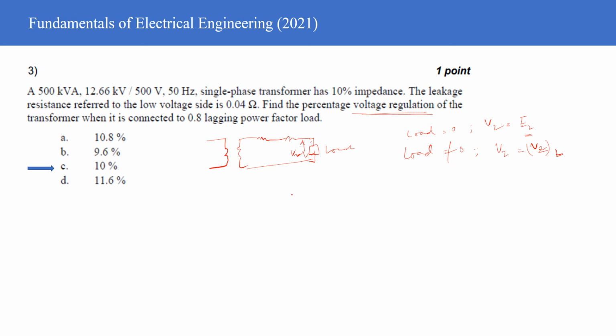Now voltage regulation is nothing but E2 minus V2 under loaded condition, divided by E2. This is your voltage regulation.